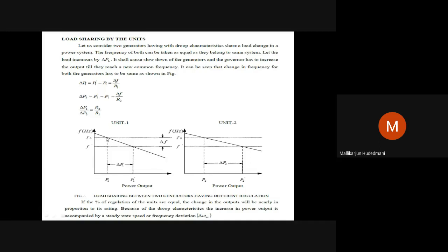Say 25% of its capacity is taken here, then 35% or 40% of its capacity is taken and dealing P2 megawatt, and this is dealing P1 megawatt. At base frequency F0, when I project this line, it intersects both the lines. With line 1 of machine 1, P1 is the output in megawatt, and P2 is the output of the second machine. If I add P1 plus P2, that becomes the total power delivered by these two units in parallel. That is the basic concept at F0.